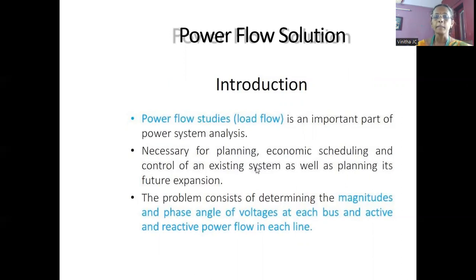The main information obtained from load flow analysis is the magnitude and phase angle of voltages at each bus, and the active and reactive power flowing in each line. All those parameters are calculated from load flow analysis.